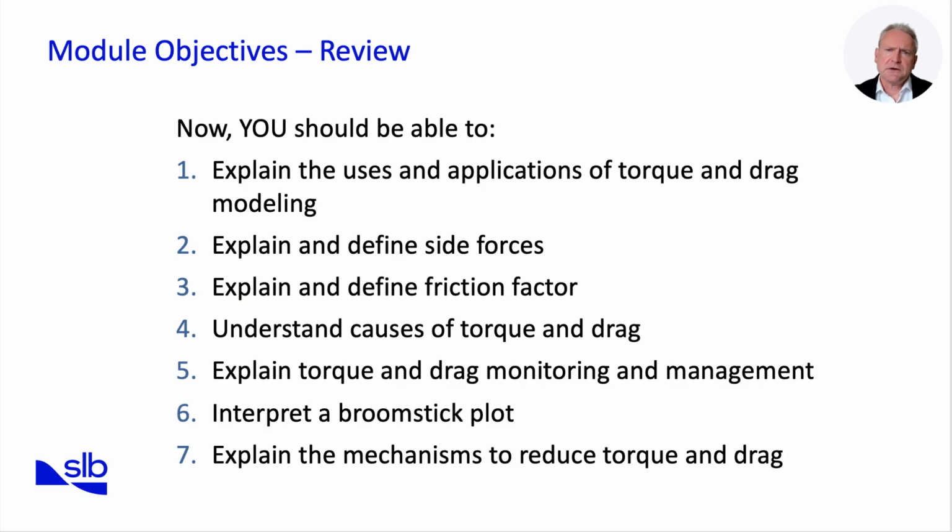Next, we compared soft string and stiff string models. The soft string model treats the drill string as a flexible cable, continuously in contact with the low side of the hole, but it underestimates torque, cannot capture buckling, and ignores mechanical integrity. The stiff string model, by contrast, incorporates bending stiffness and discrete contact points, making it the preferred approach for torque and drag analysis.